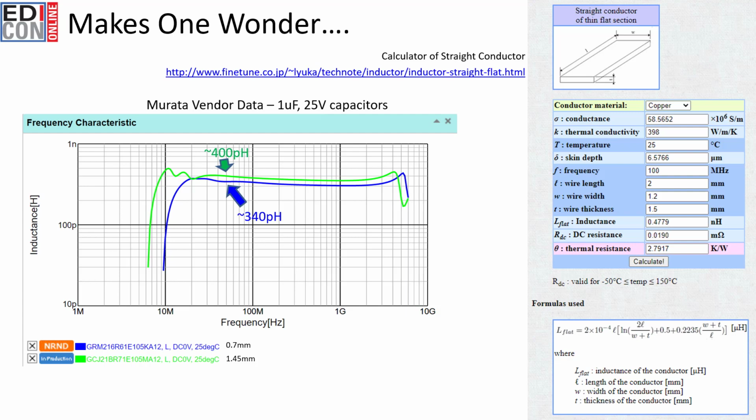This is also likely a probe contact point measurement on the capacitor pads, which will be shorter than the full 2 millimeter length of the capacitor body. In other words, the length inductance is different. As a note to reference, the PCB pad center to centers are 1.9 millimeters. That'll be important in the next slide.